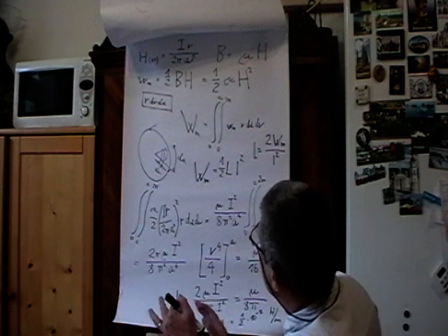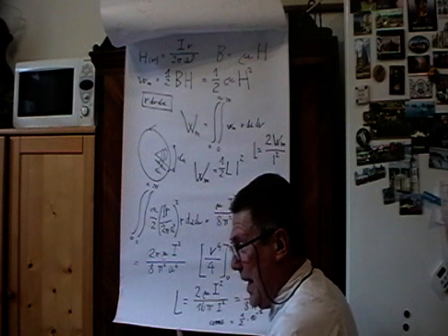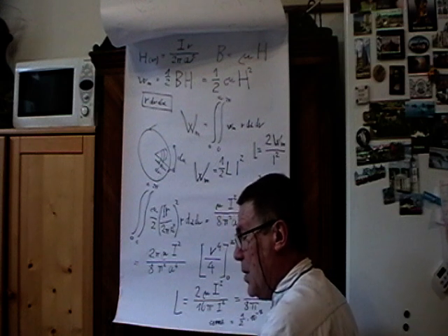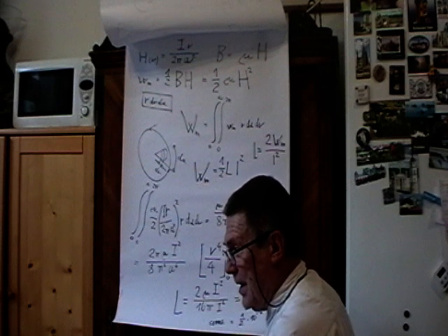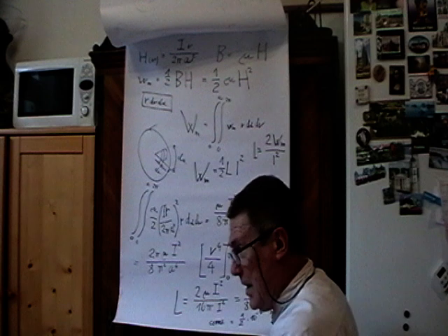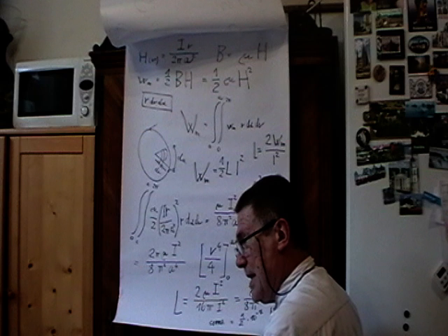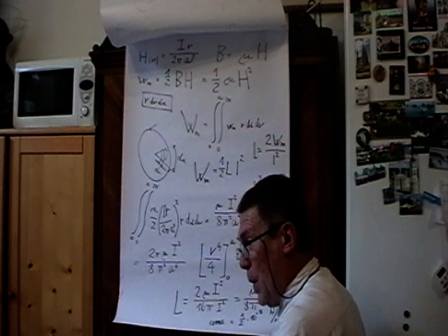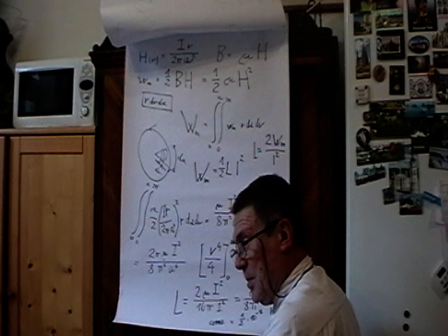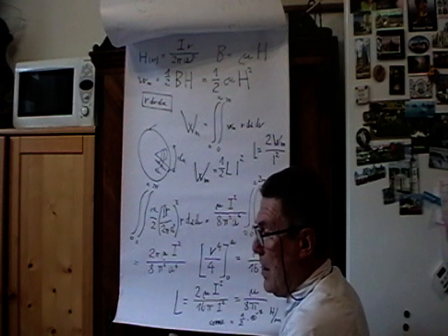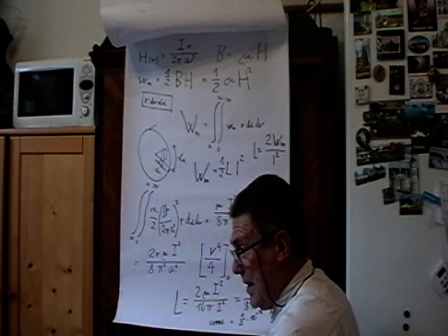So if I can summarize a little bit, we have distinguished between external and internal inductance of a conductor, the external being caused by the magnetic field caused by the current within the conductor outside the conductor, and the internal inductance being caused by the current flowing through the conductor inside the conductor. Especially at DC, the second one might be important.